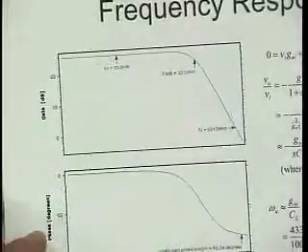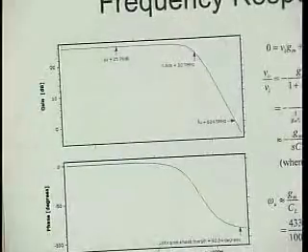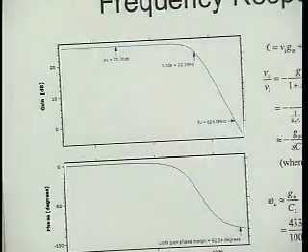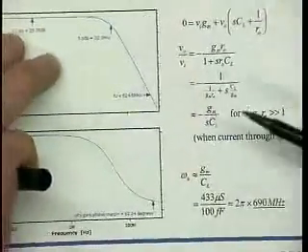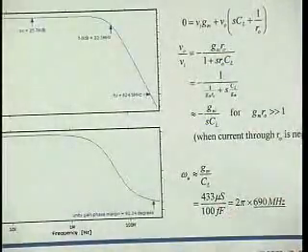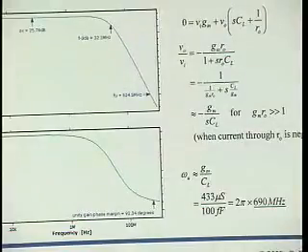Okay, then the frequency response. We evaluate that. Nothing particularly profound in here, with the exception, I want to again alert you to how we analyze this thing. Right? Frequency response, the unity gain bandwidth, or the gain bandwidth product of an amplifier that has reasonably high gain, is really determined by the transconductance and the load capacitance, not by ro. Why? Well, because